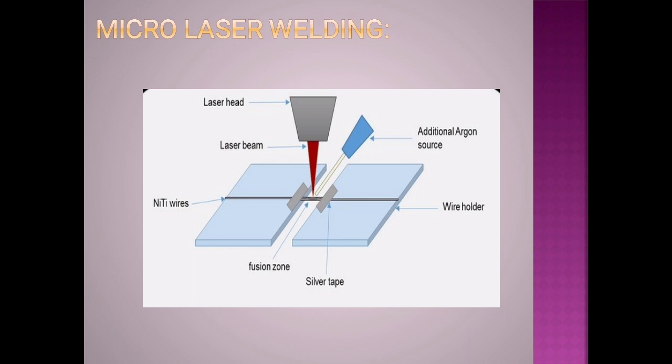The mechanism of micro welding can be explained by the heat transfer. In the welding process with low power lasers, the surface of the workpiece absorbs the laser energy and this energy penetrates into the material through thermal conduction. This imposes a limit on the penetration depth. This depth can be increased by the use of continuous wave mode lasers, but then the process becomes slow and the heat spreads to more areas.